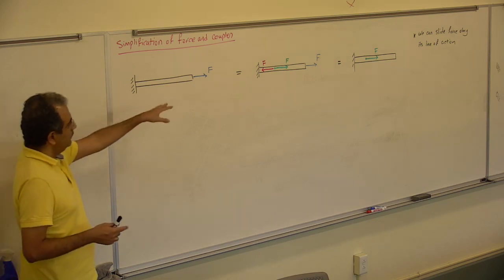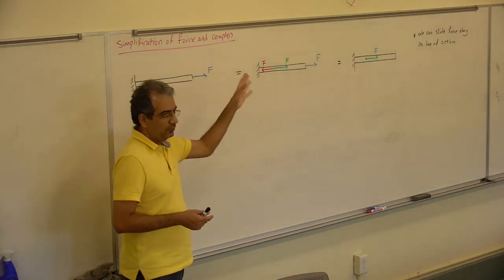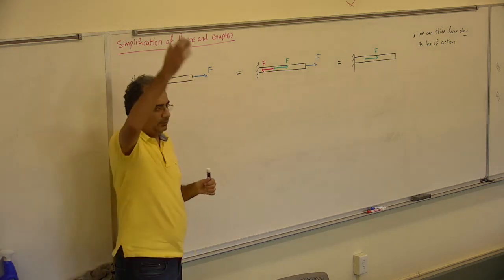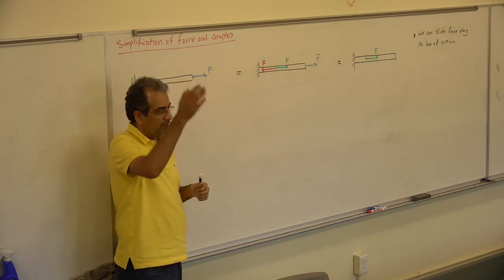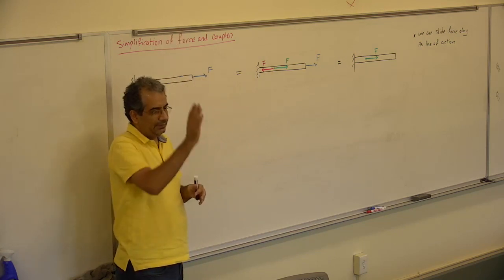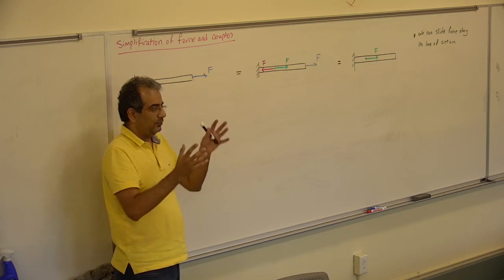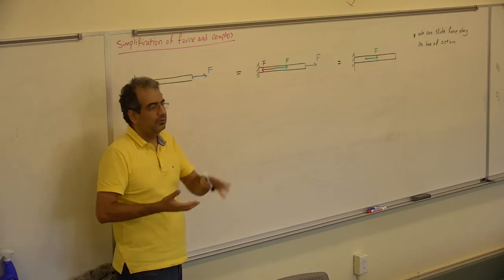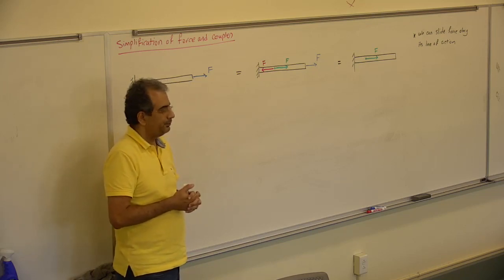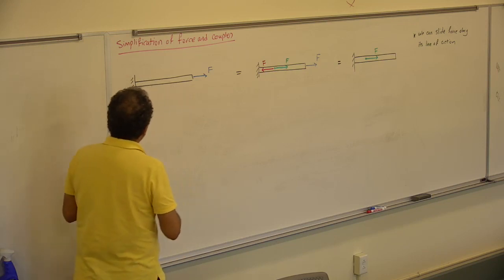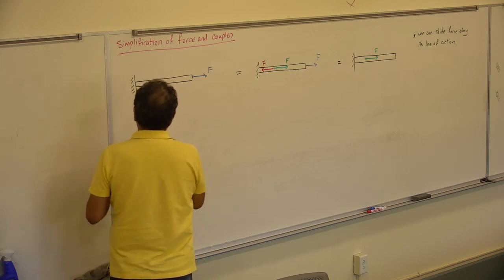So we use that a lot when we wanted to calculate the moment. We slide the force back and forth to see where's the easiest way to calculate the distance or to understand which direction it's going to rotate. Now let's look at another one.